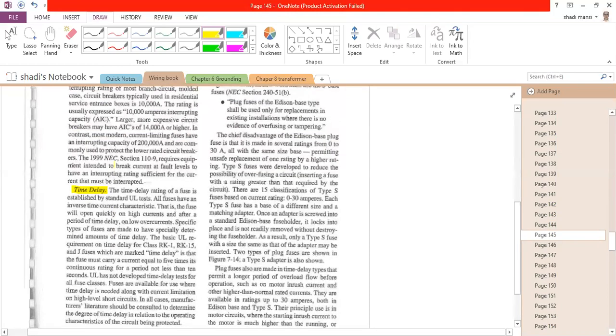By the way, it is very important to mention when we are talking about the plants in المصانع, which is not included in this course because we are talking about commercial loads. When we are talking about the plants and we are designing the electrical system, one of the most important elements is to design a protective strategy. So where do we put the circuit breakers, what are the circuit breaker numbers, their types, their locations, their ratings, the delay. What does the delay mean? For example, this one has to trip within, let's say, 50 milliseconds; the one behind it, which is the second defensive line, has to trip after the 50, for example after 70 milliseconds, and so on.